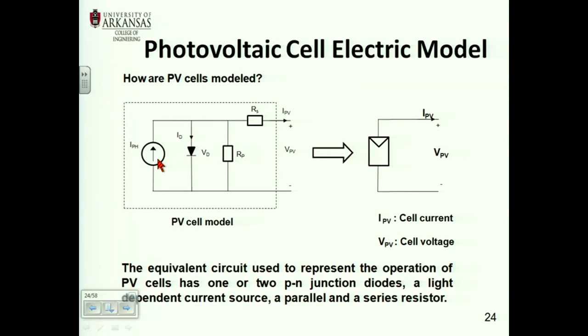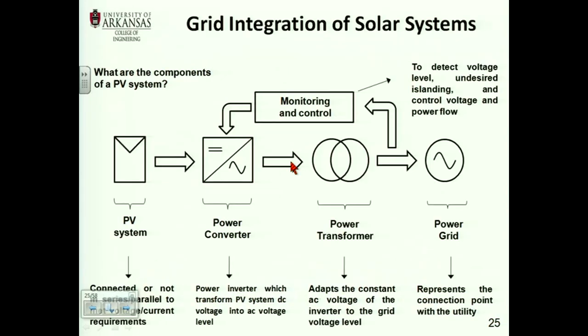And so what you do is you have many of these solar cells that you stack them up in series, right? So when you are talking about a 36-volt solar panel, you can figure out how many of those solar cells are stacked up in series. And how do you get the current? You put solar cells in parallel, right? So basically this is the symbol for a solar panel, or a solar cell, right? And that's photovoltaic, that's what PV stands for. And basically that's the model that you have.